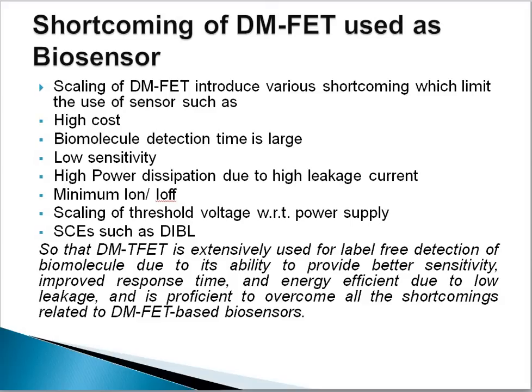These factors reduce the sensitivity of the dielectric modulated field effect transistor biosensor, so we have introduced the TFET based biosensor. The dielectric modulated tunnel field effect transistor is extensively used for label-free detection of biomolecules due to its ability to provide better sensitivity, improved response time, and energy efficiency due to low leakage, and it is proficient to overcome all the shortcomings related to the dielectric modulated field effect transistor based biosensor.